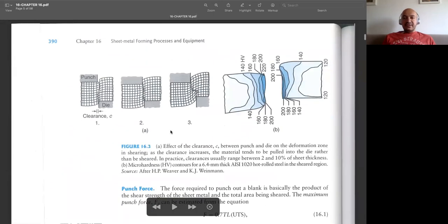You can see some numerical analysis. You can see in all of them that the clearance is highly important. If you have too much clearance, you have rougher surfaces, since it will be difficult for these cracks to meet. But if you have an appropriate amount of clearance, that is much better. If you look at the first one, I think we have less clearance, so you get weird shapes on your resulting workpiece.